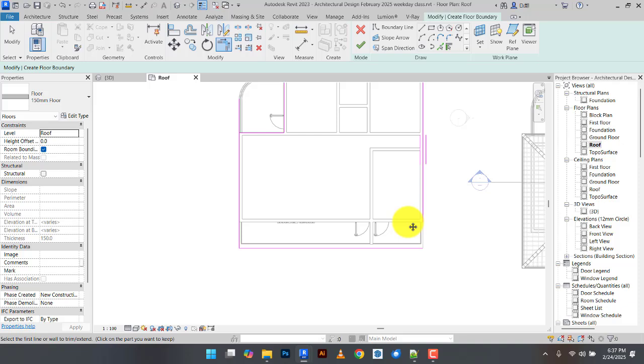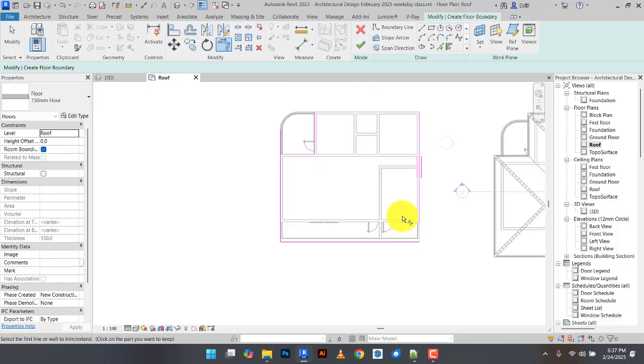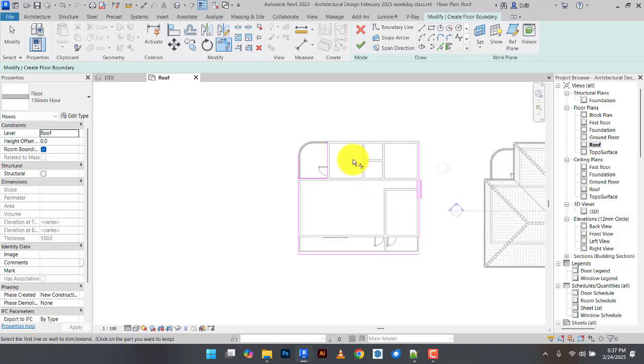So it means you have to draw another line inside. Are you with me? To draw that line, when we were doing the fascia, we drew it around the fascia, then we came to pick the wall. But here, there's nothing you can pick. So we have to offset this line inside. We offset a copy of the line, not the original line. So you click on offset and you choose your offset value.